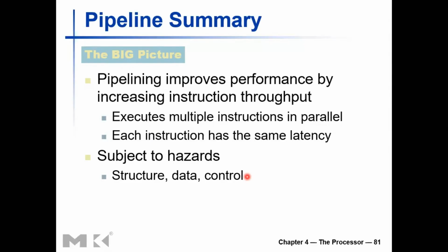So because of that, we need to stall the pipeline. We need to insert bubbles. So that is unproductive work we do with the hardware, right? We let the hardware idle for certain clock cycles, certain hardware are idle. So that was to avoid hazards.